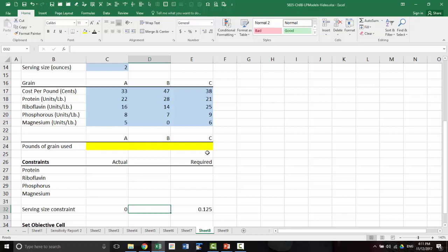So you have to put a label equal to, but if you put an equal to sign in Excel, Excel will think it's a formula and will expect a formula. So how do you force Excel to accept the equal to sign as a label? You put a single quotation mark and then your equal to, then Excel will treat this as a label and let you enter the equal to sign.